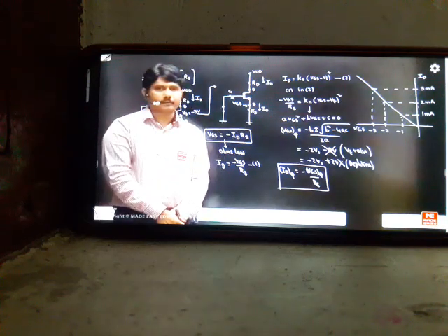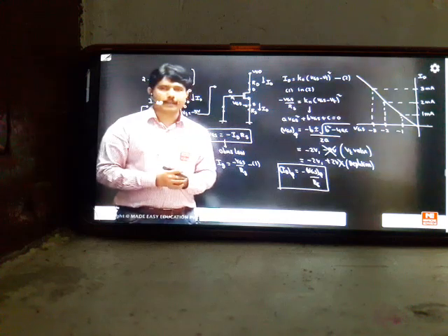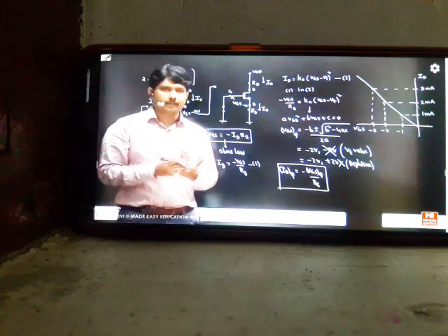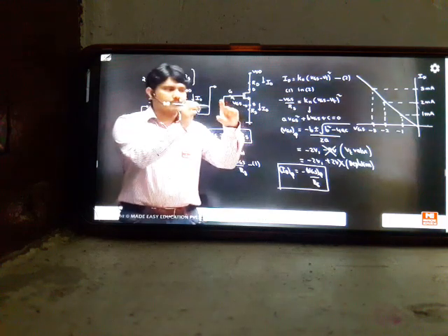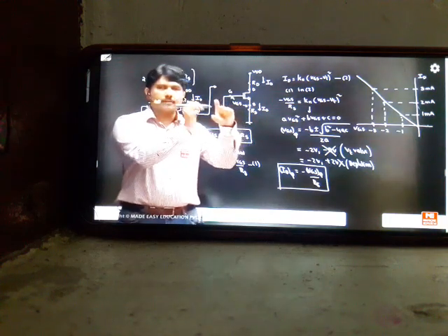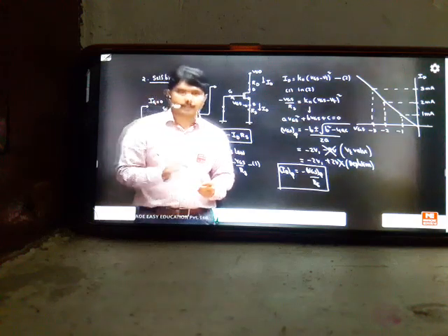And then there is one more doubt that most of the students will get. Whenever the question says IG is 0, RG is not open, my friend. The examiner gives RG as 1 megaohm. What is really open in the circuit is not RG, your input is open. Your MOSFET is open at the input, meaning no current is going into the MOSFET. There is some resistance in series, but since IG is 0, the voltage drop across the resistor will be 0. That I am telling you.